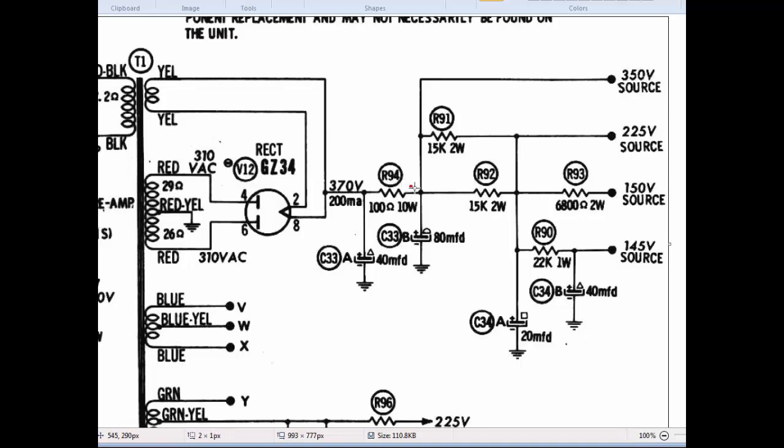In other words, the 350 volts right here dropped across both of those resistors yields you 150 volts left over. Which means that somewhere along the line here, we lost 200 volts across these resistors. And that's what their purpose is. That's not a bad thing. It's why they're put in place. That's what they're designed to do, is to drop voltage.